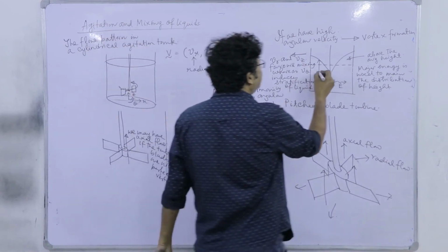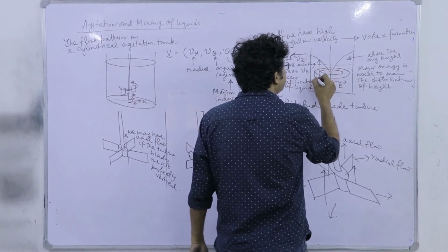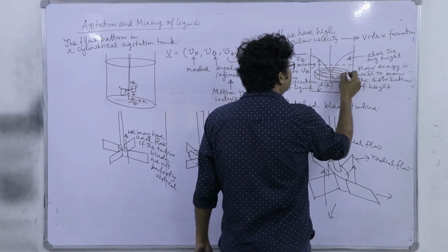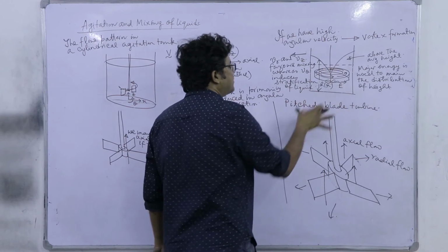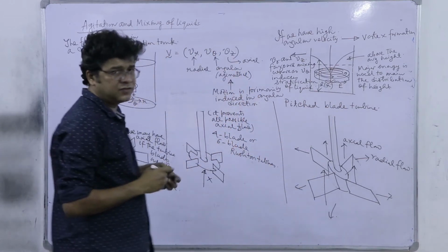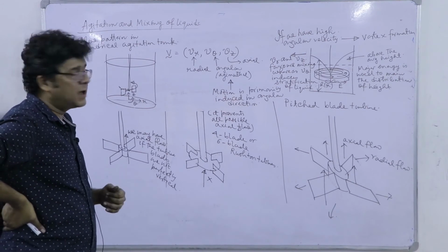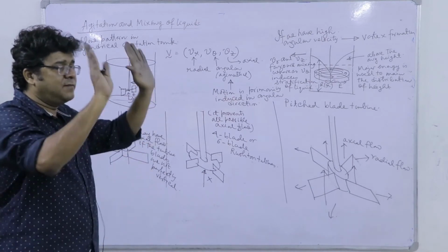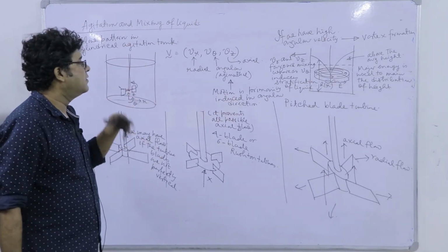Like we can think of a torus-like shape here, where the liquid circulates without interacting with other similar shapes or liquids inside other similar shapes. So that basically impedes and hinders the process of mixing, whereas if I have high V theta and high Vz, then definitely the mixing is promoted.